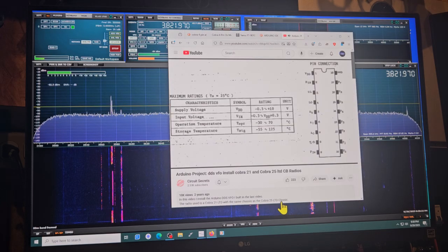On this chip, the transmit lock is labeled as LD, or lock detect. In the datasheet, I find the LD is set low when the PLL is out of lock. Low logic state is considered ground. High state is whatever the PLL runs on. I believe in this case the PLL runs on 7 volts.